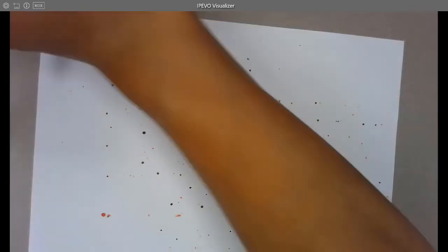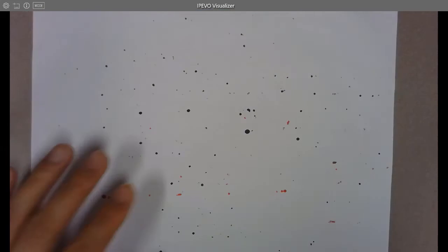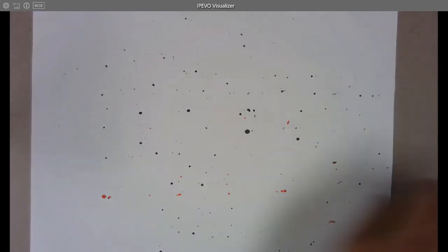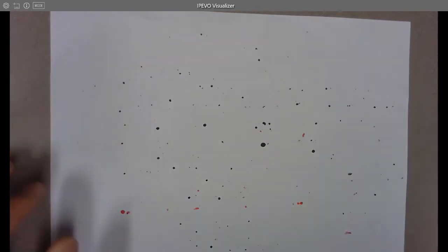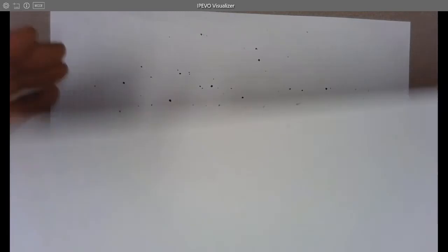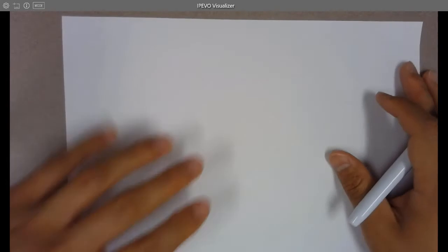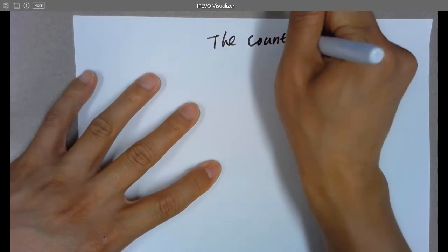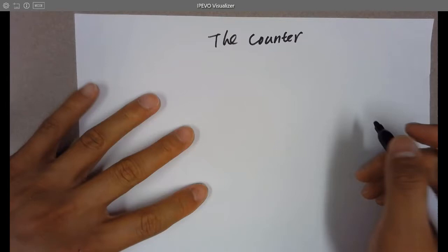And there are pretty important applications for JK flip-flops. That's why we learn it, right? The first one I want to introduce to you guys is a counter. You can use the toggling function of the JK flip-flop to design a counter from it, and you'll find out what that looks like.